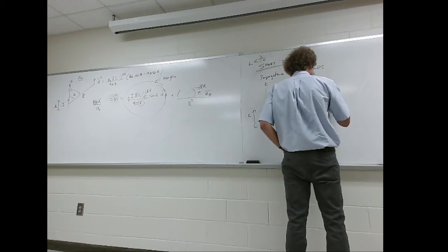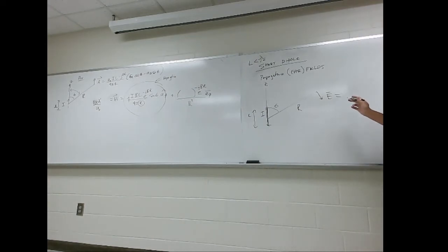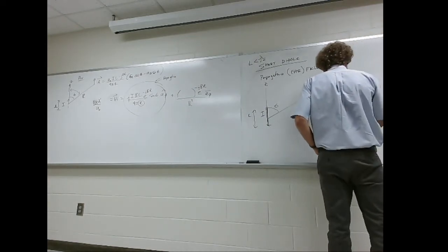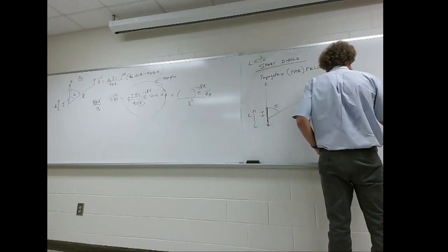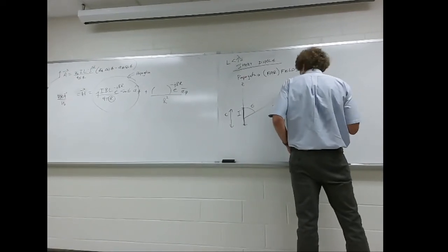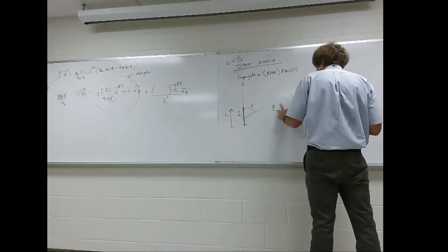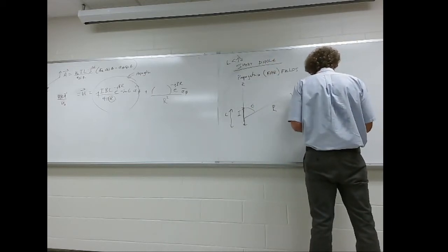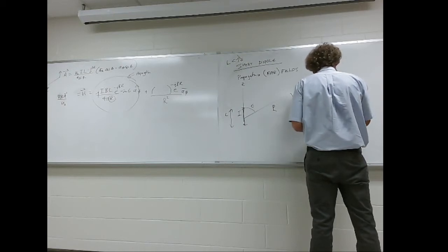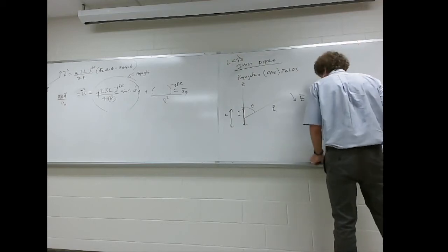The electric field, in the far field, these are far field quantities, and this is in your book. The way Dr. Whitworth gives it is j eta beta I times L over 4 pi r, and r is the range to this point. In the book, he often uses a small r to designate that range. It'll always have a phase constant of e to the minus j beta r, and it will vary as the sine of theta, and it will be in the a theta direction.